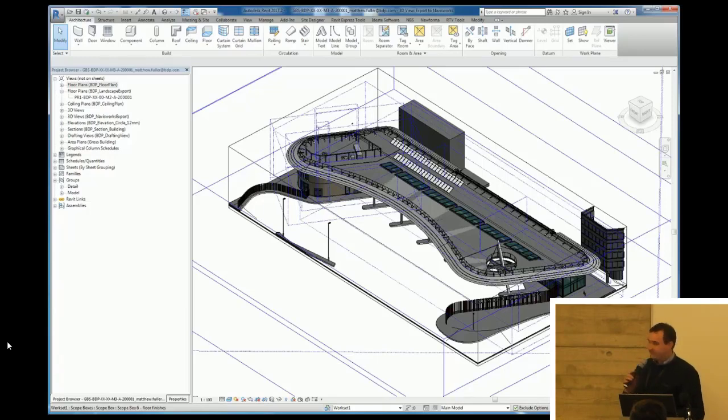Right, so this one's about Navisworks Exporter, which helps your workflow between taking a Revit model into Navisworks. If it hasn't already installed the add-in into Revit, when you've installed Navisworks, then you can go onto the Autodesk website and just download it. It's completely free, and install it. So here are some tips and best practices for doing that.